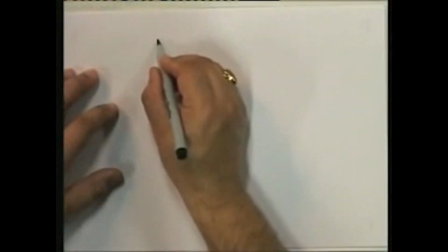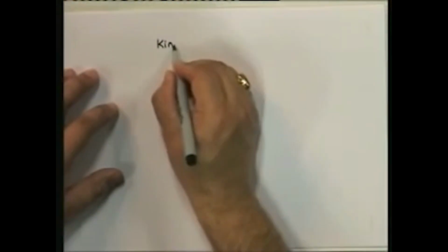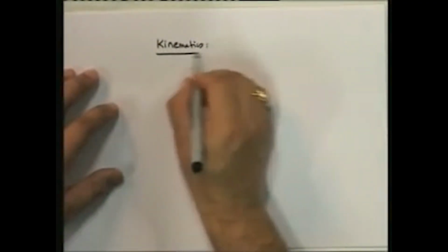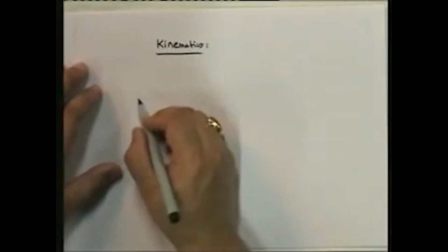See, I'm actually going through the displacement method as I have defined it. The next step is the kinematics. So what do I need to do? In terms of R1 and R2, I need to find out UAB, UBD, UCD. So next is the kinematics.